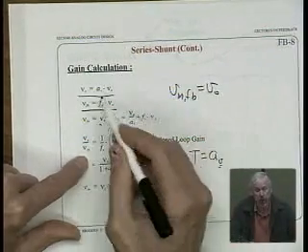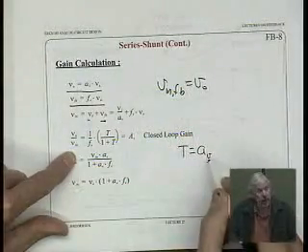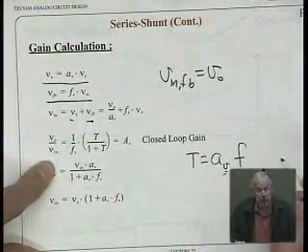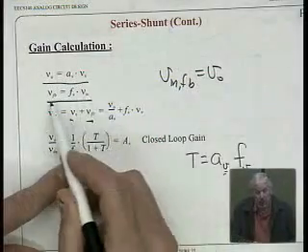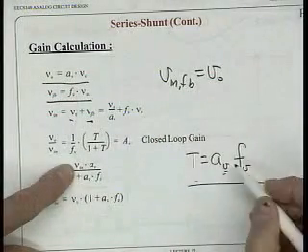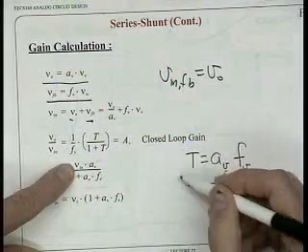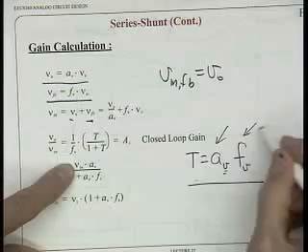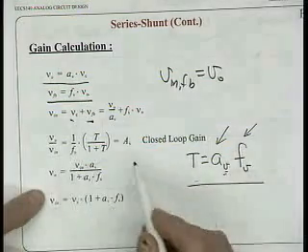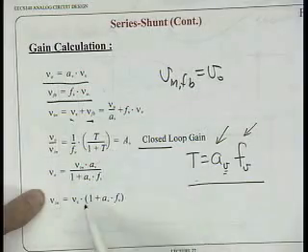Now notice the voltage. We're keeping track now of what kind of amplification this is. It's voltage amplification. It's voltage in, voltage out. So we'll have to keep track of that because we're going to start mixing currents and voltages together in a second. And times the feedback factor, which is also a voltage in, voltage out ratio. Okay? So this is the loop gain. Loop gain is always unitless. We will find sometimes these will have units in a second. Okay. All right. Okay, so this is the closed loop gain: 1 over the feedback factor times T over 1 plus T.